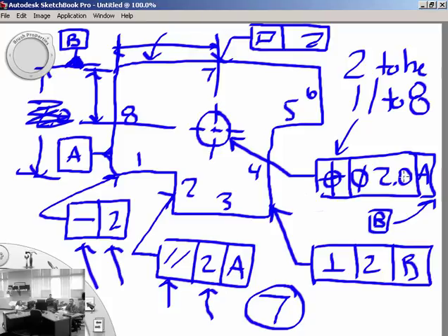Let's say that hole is supposed to be, I don't know, 27 units this way and 16 units this way. You have to know what those dimensions are to be able to check what the true zone is supposed to be. So they may add the datum references, saying you're coming from B down 16, you're coming from A over 27, so you use these datum references to check the actual true position. You may see a true position on a set of plans that has datum references. You also may see a true position that doesn't reference the datums because it's just kind of a given. You have to know what the numbers are. It could go either way. I just want to make sure you're aware of that.